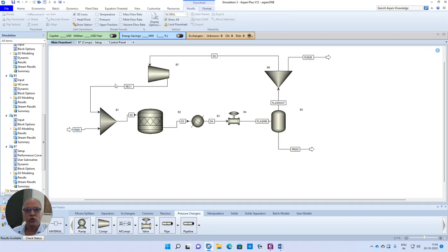See, generally, you start with an initial approximation for the recycle. When I get an updated value for this recycle stream, we compare for convergence. Otherwise, we need to start with a fresh set of values for this recycle stream. Remember, guessing values for recycle means guessing values of C plus 2 variables, depending on the number of components.